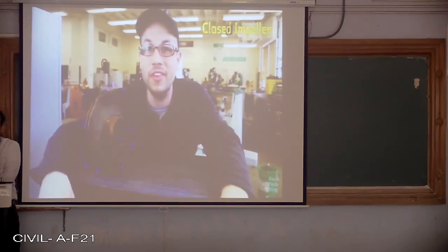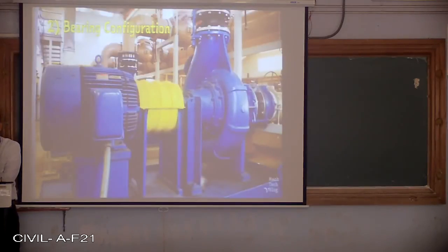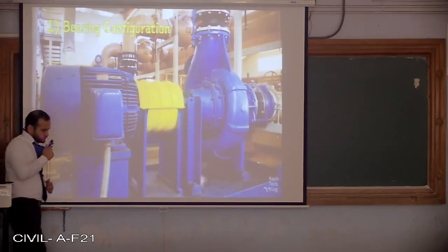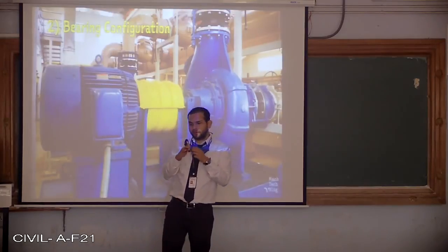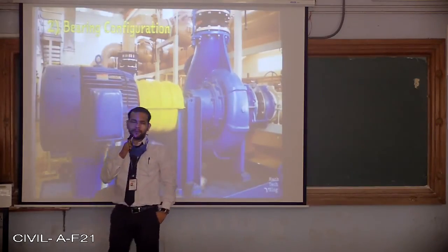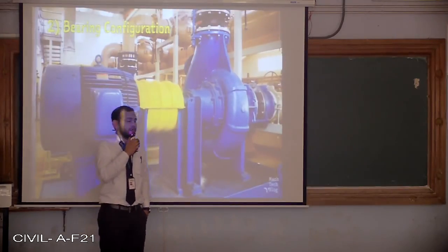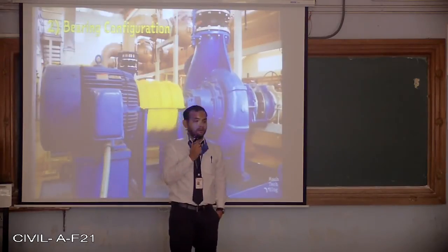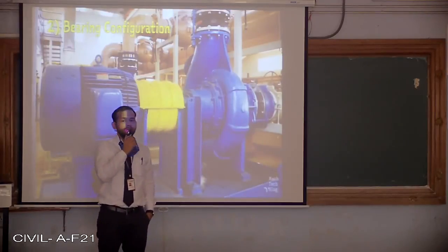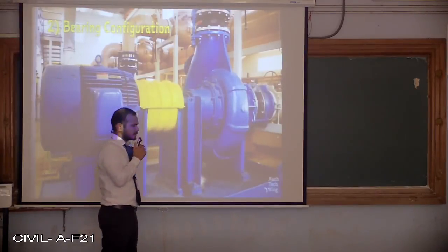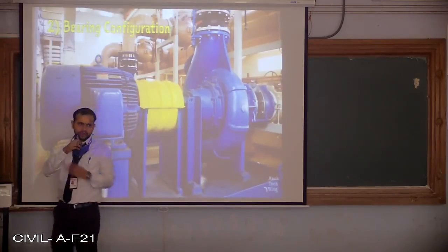Of course, the trade-off is that they can very easily get clogged with debris. Whichever style of impeller is used in a pump, basically, you have to choose the impeller according to the use of your pump. Sometimes you may just have to pump clean water, some chemicals. Sometimes you also have to use pumps for pumping concrete, or for your sewage pipes or wastewater treatment plants. So in such cases you may have some particles inside there. So depending on that, you have to design or choose a pump which is suitable for pumping.